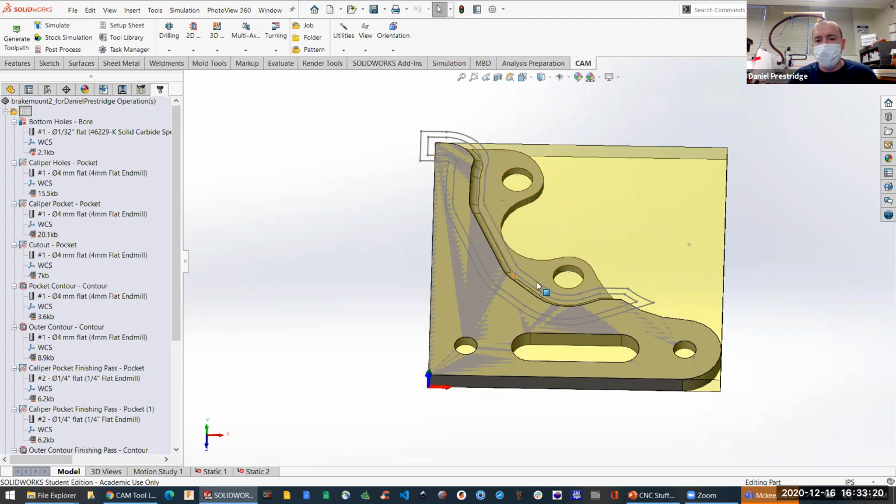But let me talk about the fixture method real quick, because I think that it's pretty important. So I told you that if you have excess vibration, what it's doing is, instead of just moving through the piece, it's like shaking the piece, or it's pulling up and hitting into it, and that's not being efficient. You can have a lot of heat buildup. You can have your end mill break if it gets too bad.